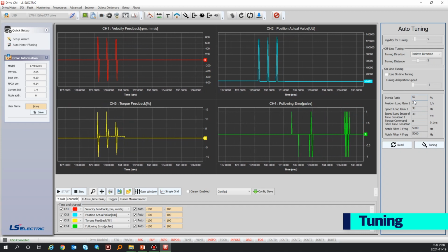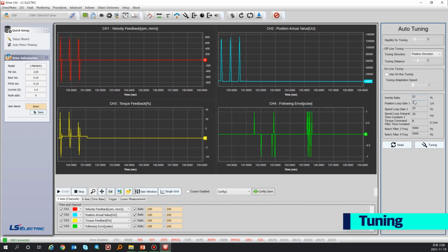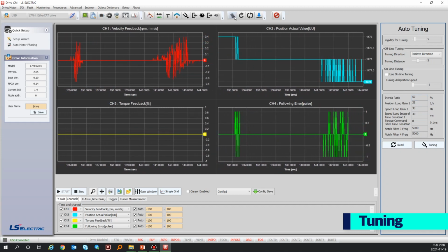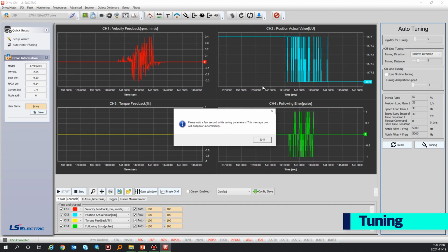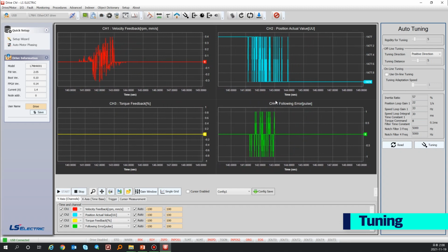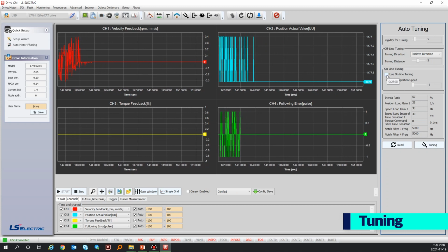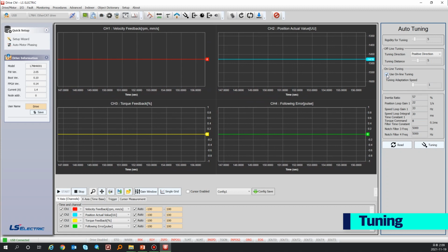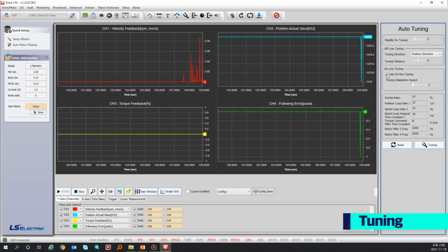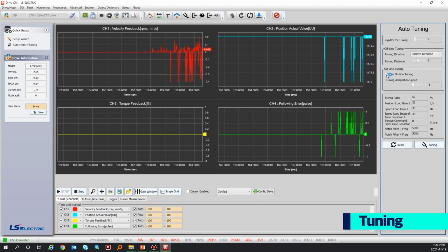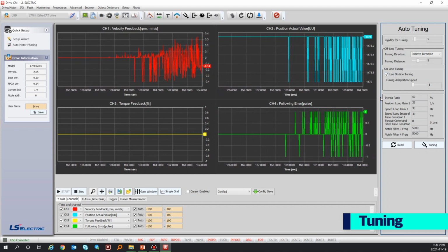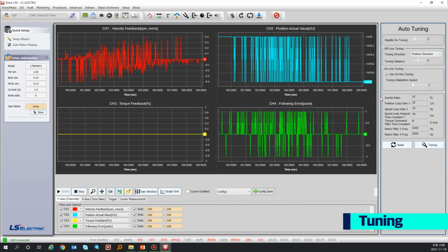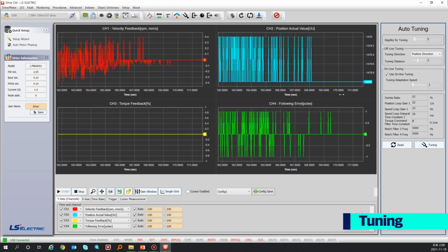After that, perform user fine manual tuning to find the optimal value. Click Save to Memory and save it to the EEPROM in the Servo drive. Also, if you check Online Tuning, you will find and apply the tuning value in real time. Depending on the rigidity, online tuning is conducted by referring to the value of the gain table in 20 stages, and the tuning result is periodically reflected, and the changed gain is saved in the EEPROM about every 2 minutes.